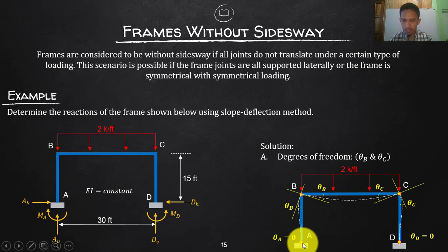because this will not deflect because of the moment that will counteract. That is supposedly bending that way, isn't it? If this is a pin, that will bend that way. So the bending will be from point A to point B. However, there is a resisting moment at the support, so the deflection here will be counteracted.